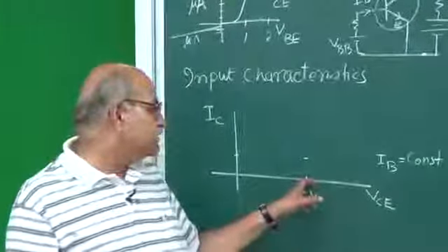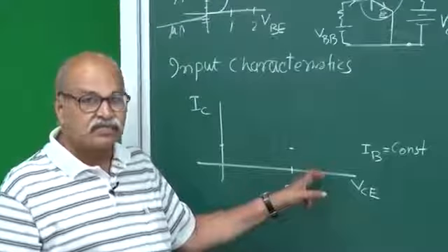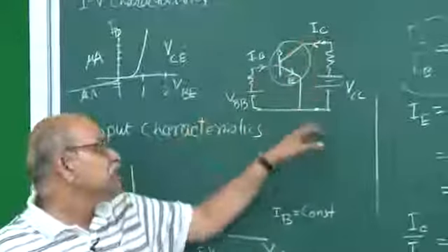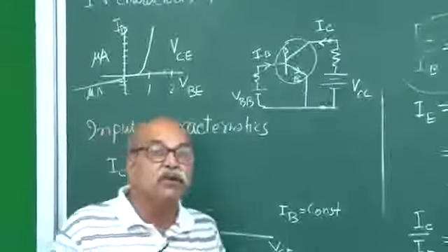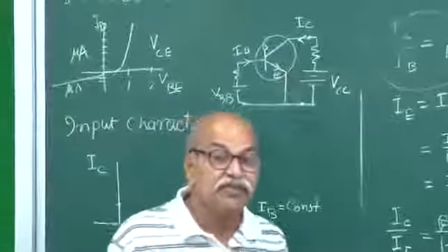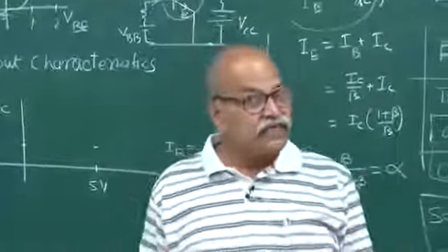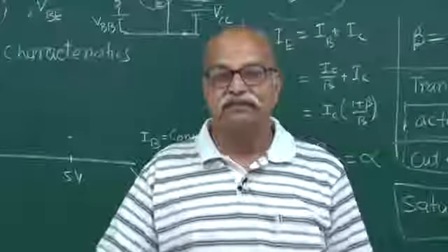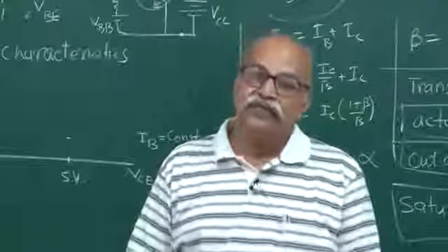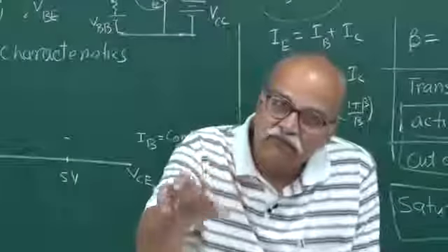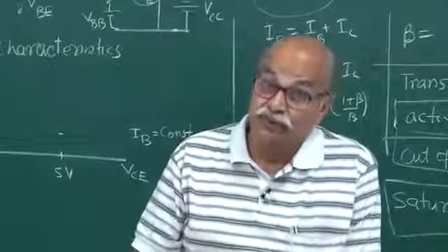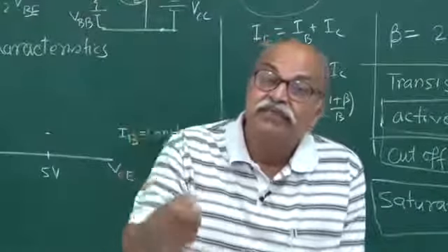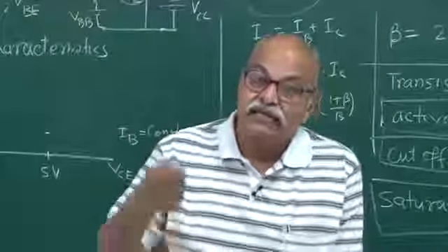What if I make this 5 volt 6 volts? If I increase this biasing here, so that this VCE increases, so it is more reverse biased, what will happen to the current? Since I said that it is already in the right region, not in saturation, it is drawing the maximum number of electrons that it is supposed to for a given IB. For a given IB, beta times IB should be IC, and it is doing that.